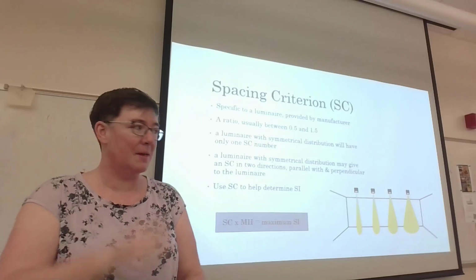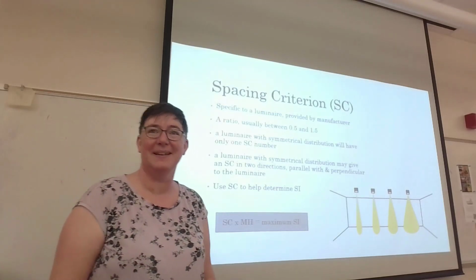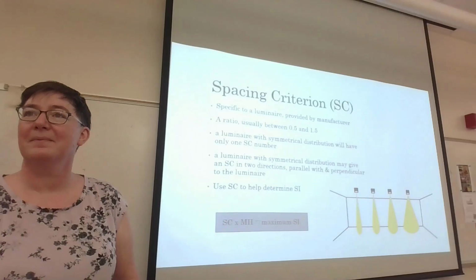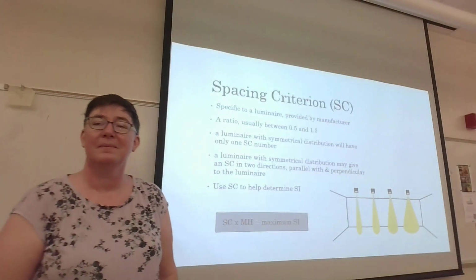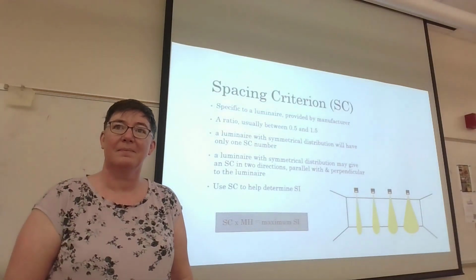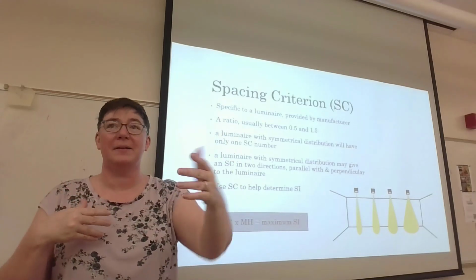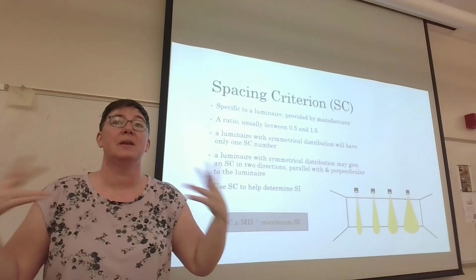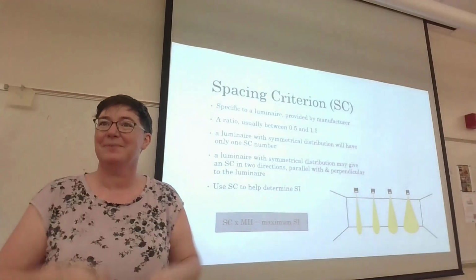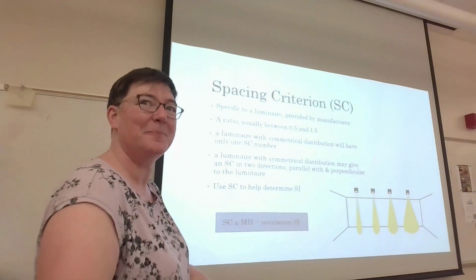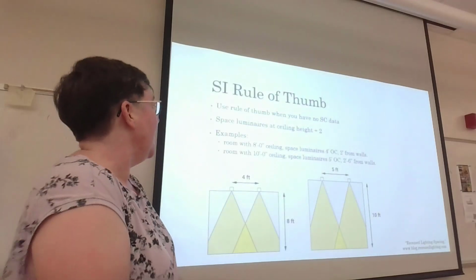If we got a measuring tape, we could find that. But yeah. We have a luminaire that's an asymmetrical distribution. We have to do the calculation twice. Correct. One in one direction, east-west in your room. One in the other direction, north-south in your room. Bingo. All right.